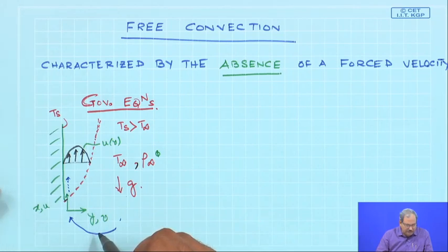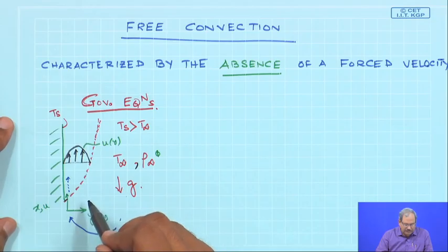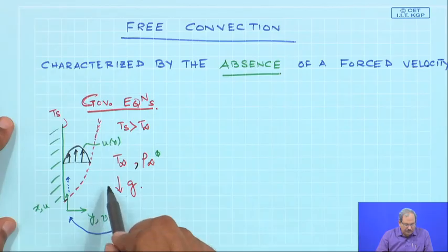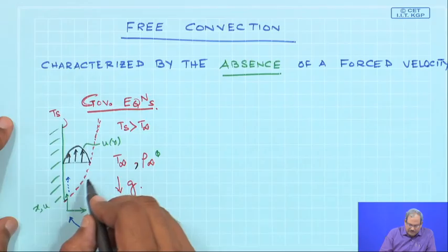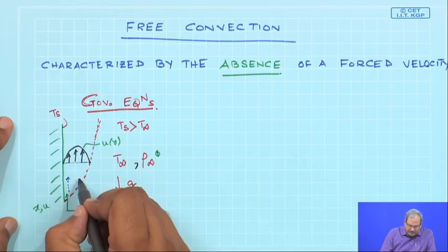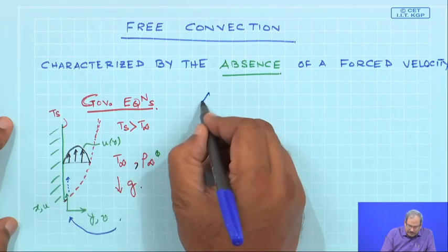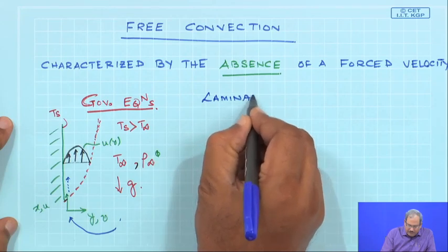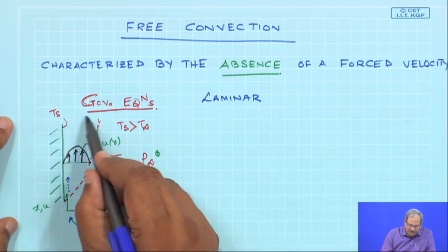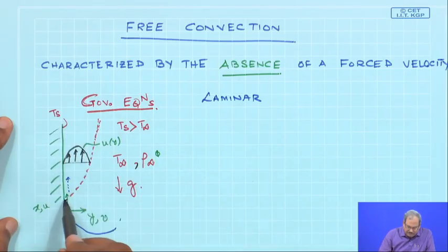So, this is what is known as free convection, and free convection flows are also classified according to whether the flow is bounded by a surface, and free boundary flows may occur in the form of a plume or a buoyant jet. Okay, so, let us write the equation. Let us assume that the density difference imposed flow inside the boundary layer is laminar, but however, it is also possible that we will have turbulence at some point at a larger value of x. So, this is x equal to 0, y equal to 0, that is the origin that we have, and the velocity in the x direction is u, the velocity in the y direction is v.